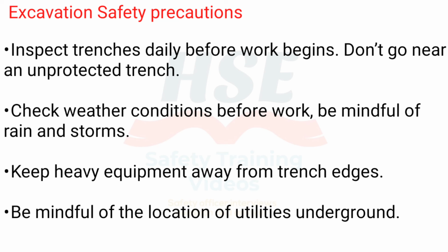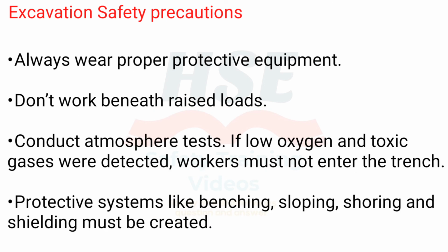Excavation safety precautions: inspect trenches daily before work begins. Don't go near an unprotected trench. Check weather conditions before work. Be mindful of rain and storms. Keep heavy equipment away from trench edges. Be mindful of the location of utilities underground. Always wear proper protective equipment. Don't work beneath raised loads.